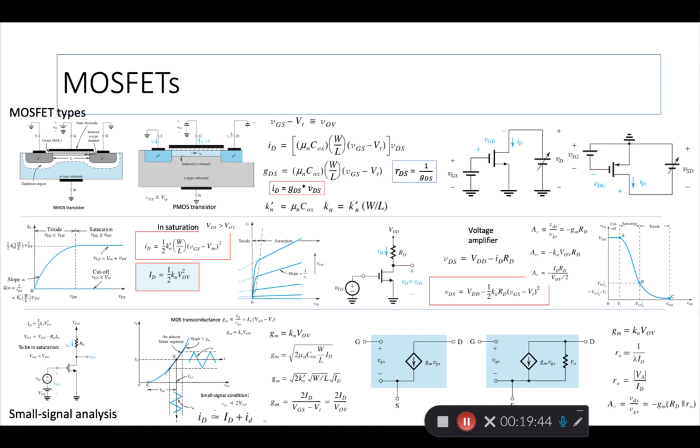Okay, so that amplification happens if you operate in this linear region between A and B, and you have a good bias point right in the middle, the Q point, so that you have a nice swing on either side of your input signal. Okay, so that was the middle row.